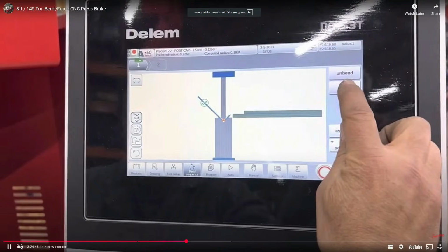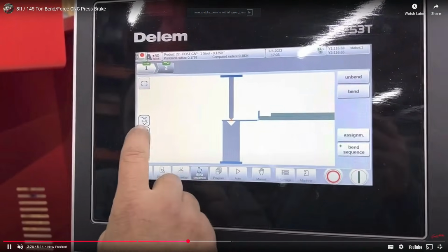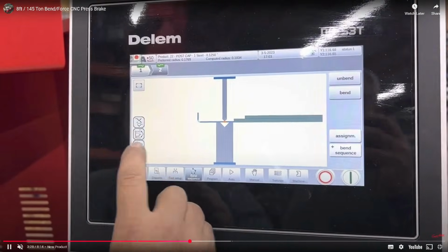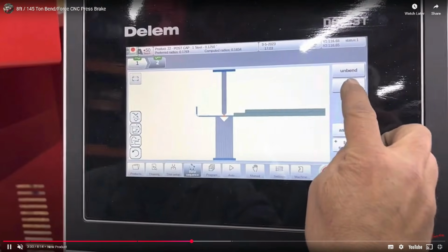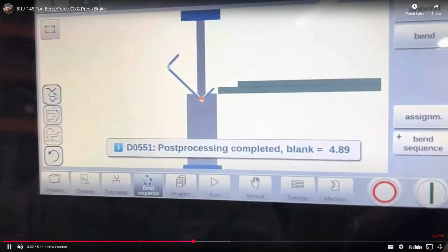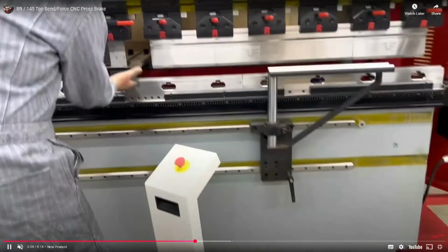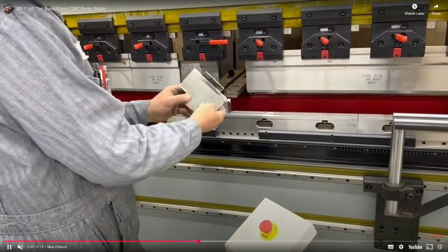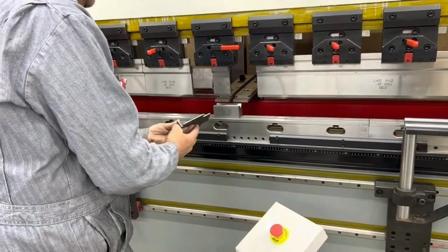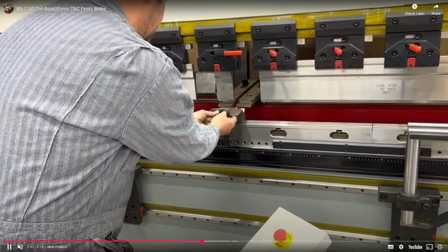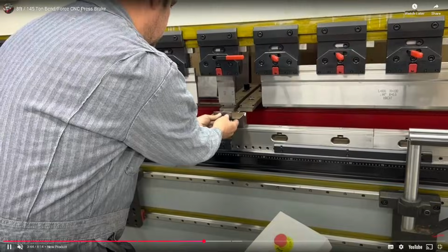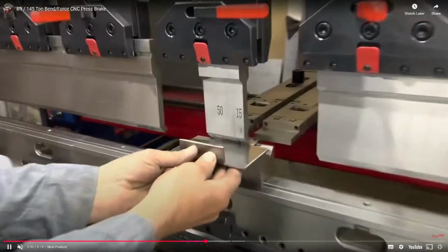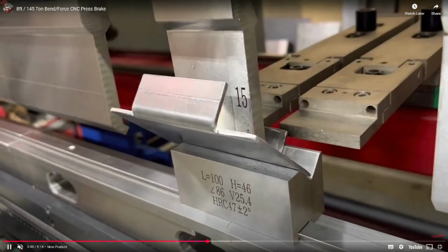So you program the cut, it sets the stop up, and it does each bend as you go through. So obviously the stop comes forward and bends it. You can't grip hold of this because it just flips it up. There's the first bend you can see here. Going to flip it round to the second side. So this little form should be just wide enough to get that thing in it. And see the stop at the back there? That will move ready for the next bend.